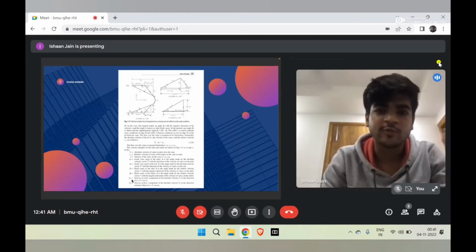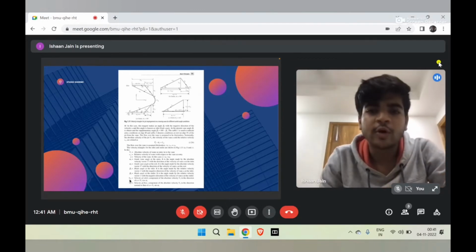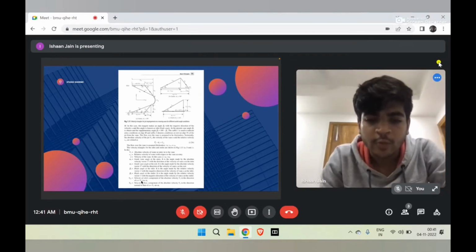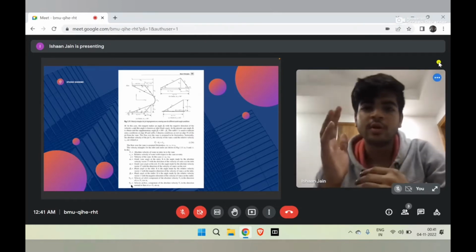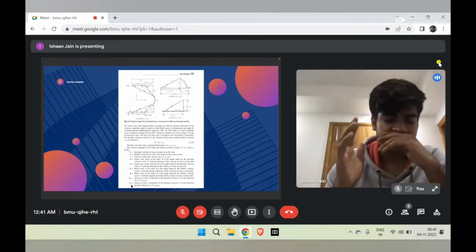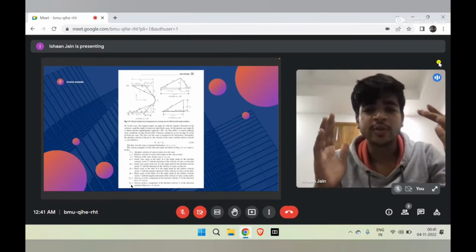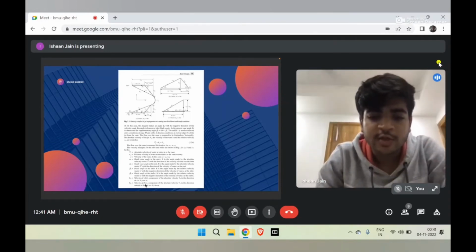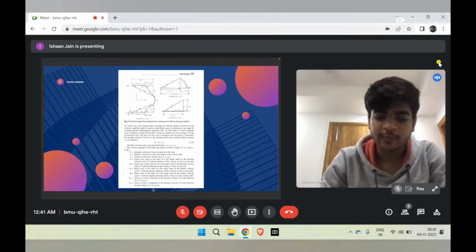which we refer to as V1 cos alpha, that we call as velocity of whirl, which is the component of the absolute velocity V1 in the direction of the U, and VF1, which was the tangential component of the absolute velocity in the perpendicular direction, which we called as V1 sin alpha. It is called the velocity of flow, component of the absolute velocity V1 in the direction normal to that of U. Okay.